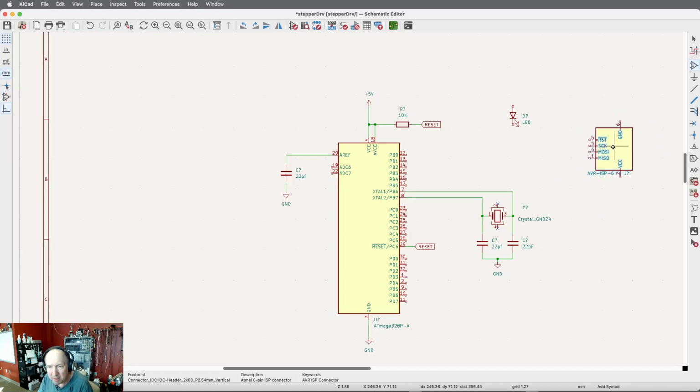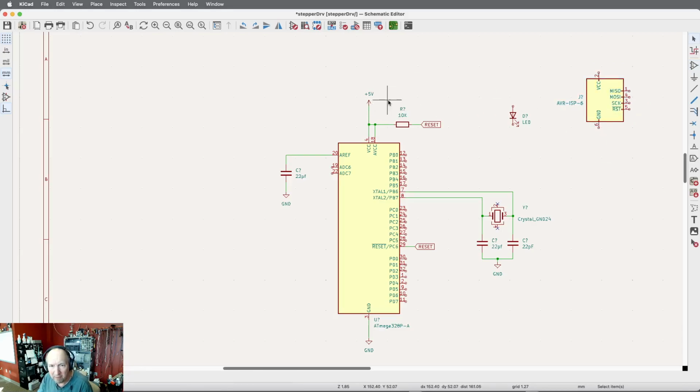And I can do the rotate button to get everything closer over to here the way I want it. So let me just put it up top. Let me just leave it the way it was. Okay, so I need VCC. Hit the escape key first. Put it on there. Duplicate the VCC. Let's put one of those up there. Come on the ground. Command D. Duplicate that. We'll put that there.